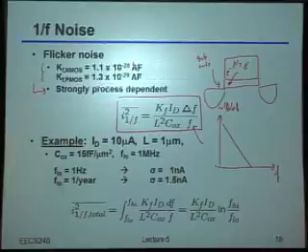And I'll give you some representative ways of back of the envelope figuring out what those numbers will be in one second. Before we do that, though, I did want to ask you guys a couple of questions. First, notice this noise current density from the 1 over f is proportional to 1 over the oxide capacitance. And just as a reminder, that Cox is just epsilon ox over Tox. So why is it that increasing that oxide capacitance decreases the effect of this flicker noise, at least from a drain current noise standpoint? What's happening there?